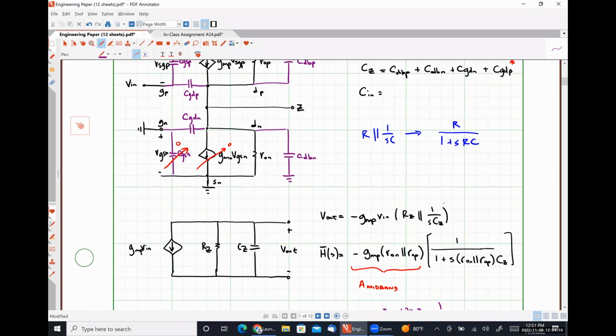So it will have some influence on the behavior of the frequency response. Since it's serving to make CY larger, it's making our output pole of our differential stage more and more dominant. It's making the frequency lower. So it's creating separation between it and the subsequent pole that we saw.